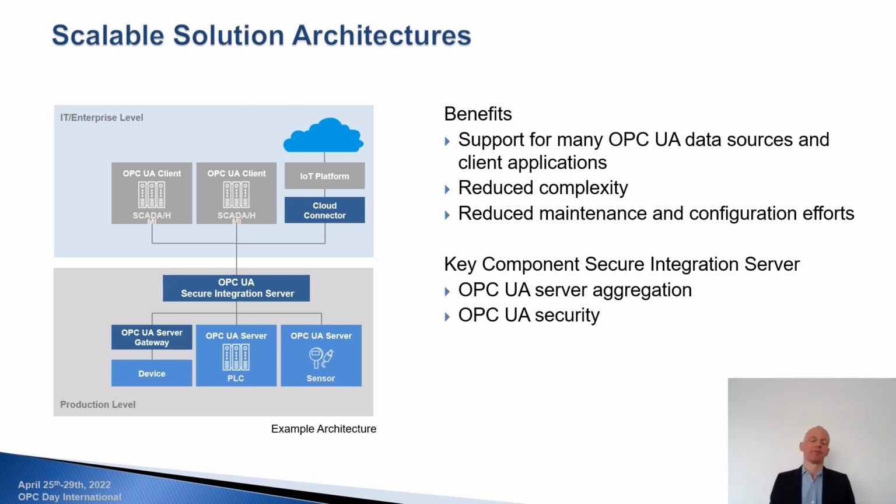So an application has to be configured only against one single OPC server instead of hundreds or maybe even thousands. And the second aspect of that image, coming back to configuration, is that it may not be necessary to use all security features in the communication between a device and the integration server. Maybe authentication is enough, but you do not need encryption.